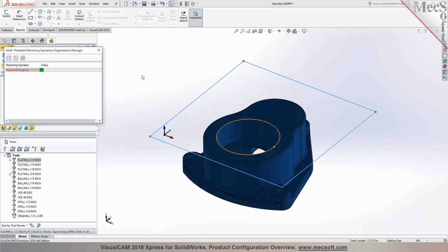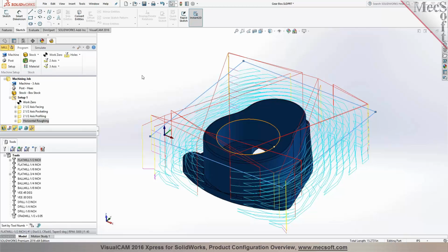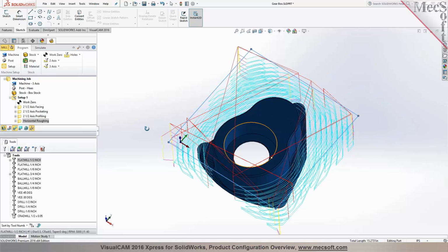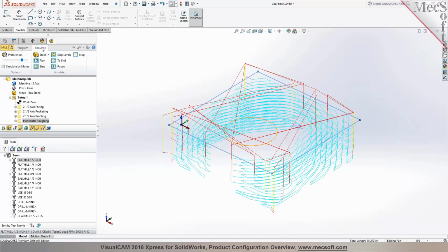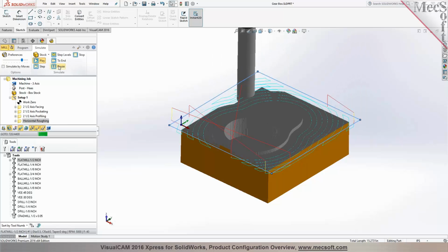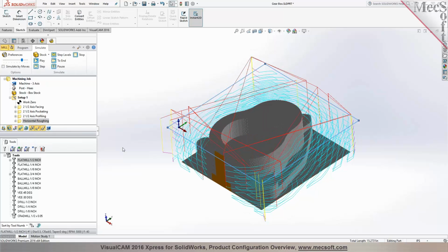Now additional options like advanced cut parameters, where you can perform smooth cut connections, arc fitting, those options are available starting with the standard configuration. And there's your roughing toolpath right there. We can now go into the simulate tab, select the operation, and pick play to run the simulation. You can always do a pause and then pick simulate to end to run through the simulation. Now since we picked the rectangle in here as a containment, you'll notice that the cutter stays up to the boundary, so it wasn't able to rough some of the areas out in here.